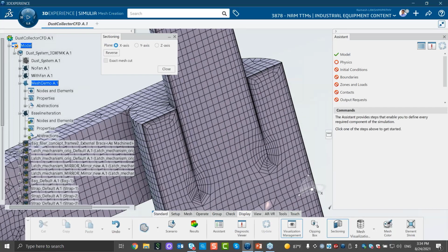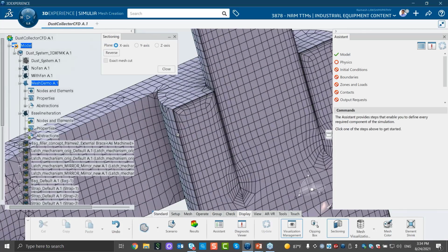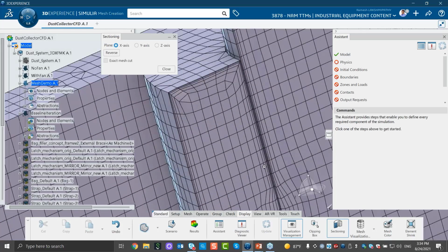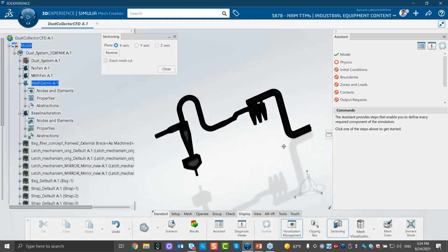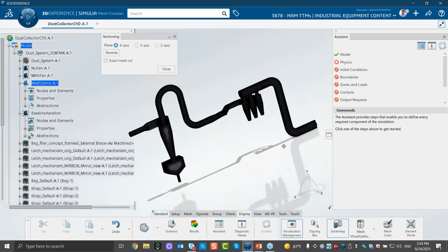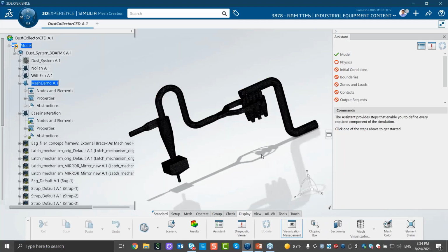It's perfect, yeah. Okay, so you can see that these boundary layers are actually a very simple thing to do in Fluid Dynamics Engineer. Especially when it comes to the meshing process, you want to capture the pressure gradients more accurately in a pipe problem like this. Doesn't matter, if you want to add boundary layers, it's a simple step. Just keep that in mind.